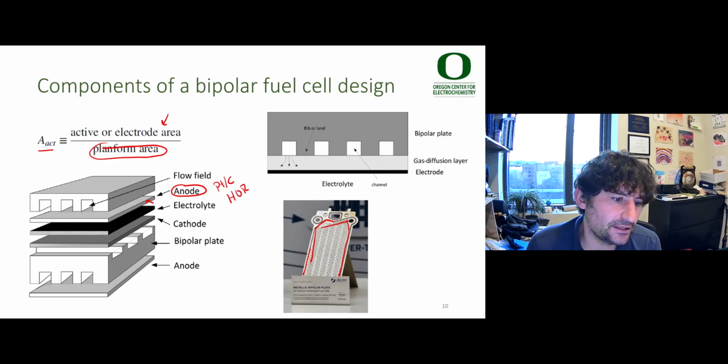So there's going to be H2 flowing in, fuel flowing in these channels to supply it. It's going to move vertically here. It's going to flow across the channel, but then be pushed vertically and consumed in the anode. There's the electrolyte phase. Again, in a PEM system, this is typically Nafion. As I oxidize those H2 molecules, I'm going to make H+.